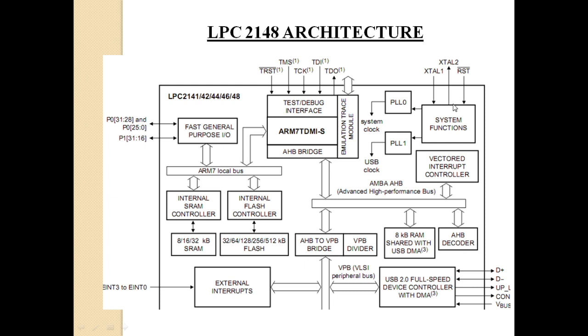From the controller, it will be given, say for example, a pilot clock to the crystal, or it will give a small frequency clock to the crystal, right? So whenever it is getting a small frequency signal, the crystal will start vibrating at its fundamental frequency, or whatever you can call it, the desired frequency.